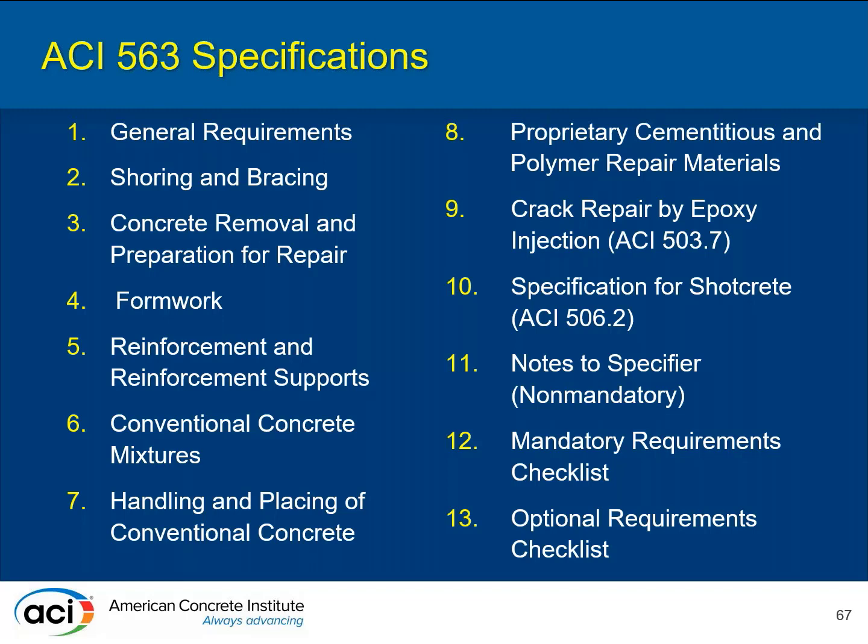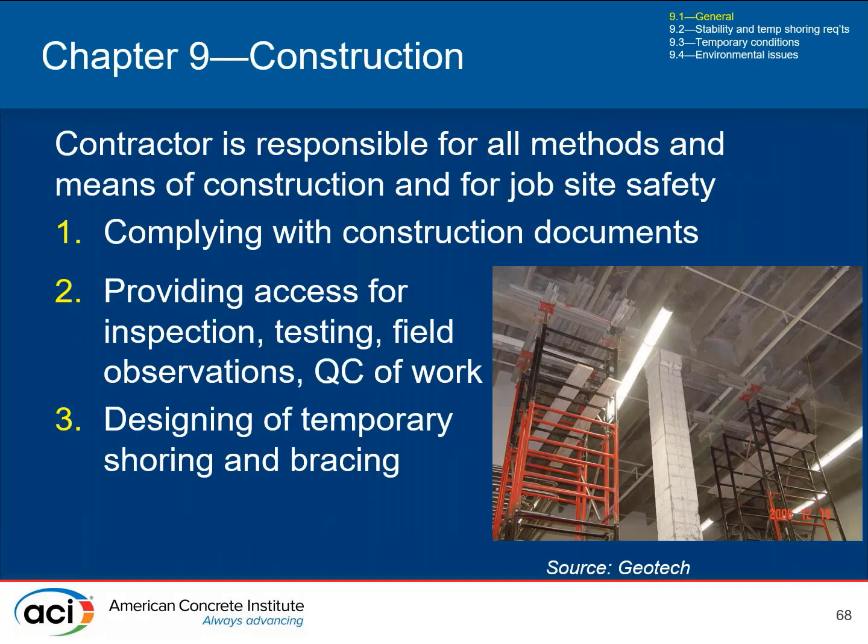If you're in the repair industry, these are very useful to be familiar with, either to use on your projects or to develop your own specifications and see what's important. Again, very similar in many ways to 318. The contractor is still responsible for means and methods and job site safety. That does not change. They're responsible for complying with the construction documents, providing access for QC and inspection, and are responsible for designing temporary shoring and bracing.